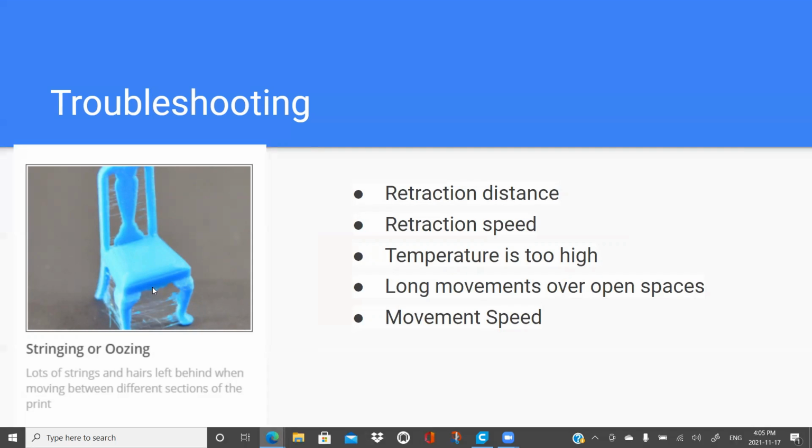You can change this on the interface of your 3D printer. I'm not getting too specific with the interface because it does depend on the exact models you're using, but it is pretty obvious. It's basically just like a screen at the front of the printer. So you can change that retraction distance and increase it there.